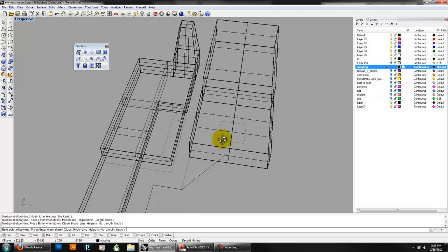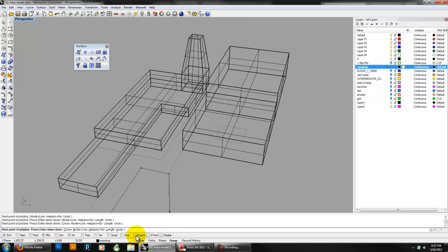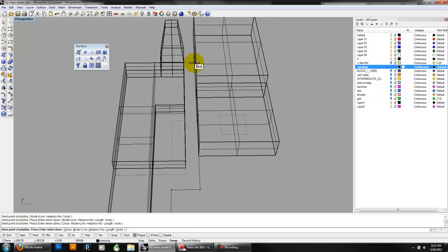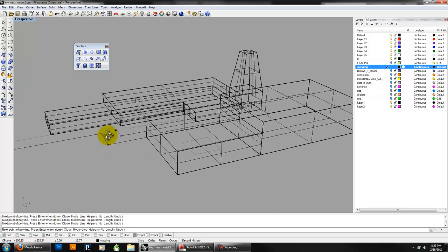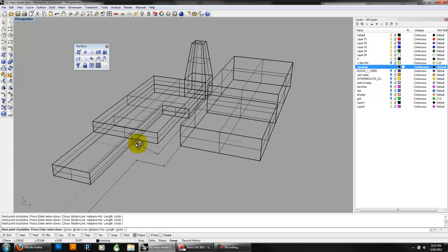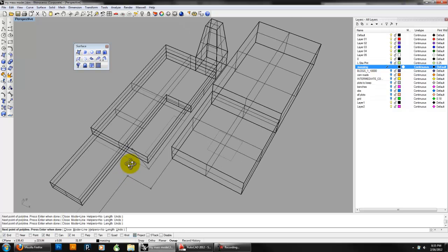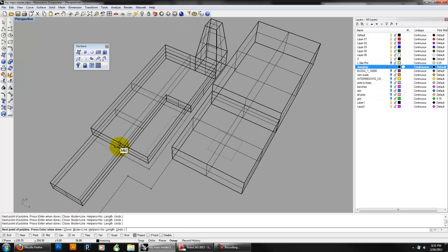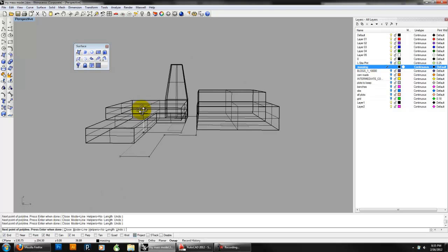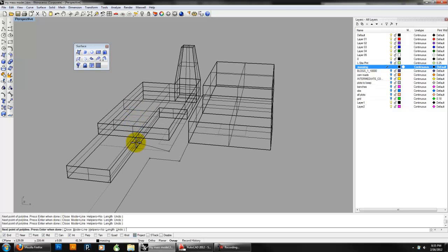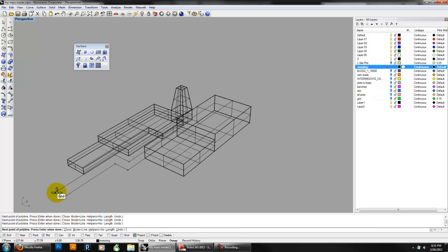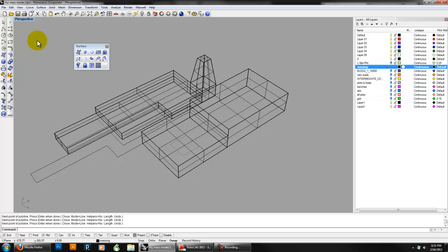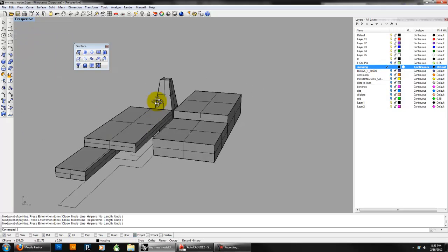And if you're having trouble snapping to things in plan, I would turn on project, and that's going to project all lines to the coordinate plane, which is 0, z. So even here, this is interesting. Even if I use this, I can snap to the end of it. That's what that does. You can snap to things in different coordinate planes, and they'll actually drop to z0.